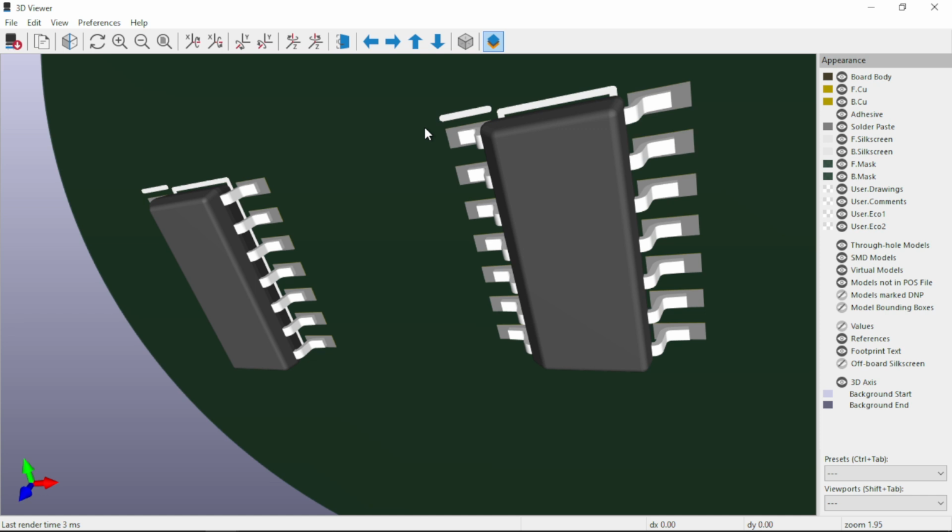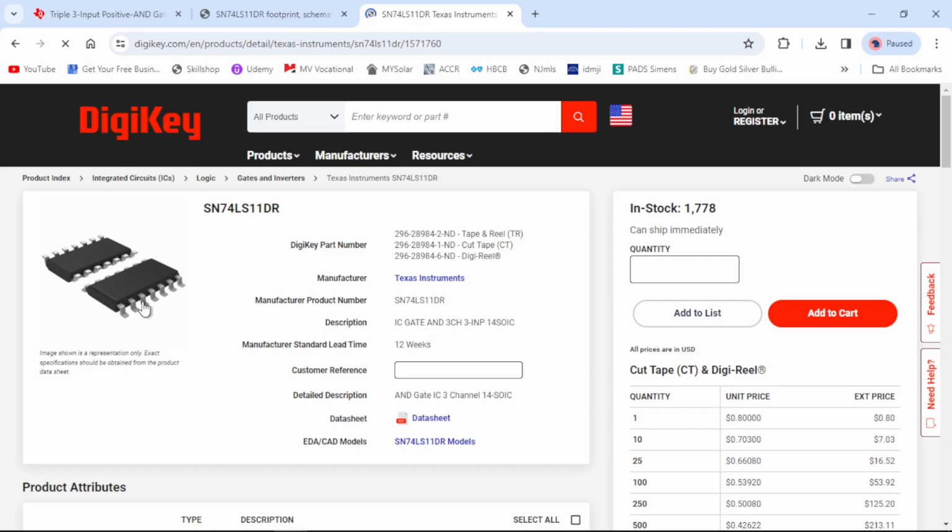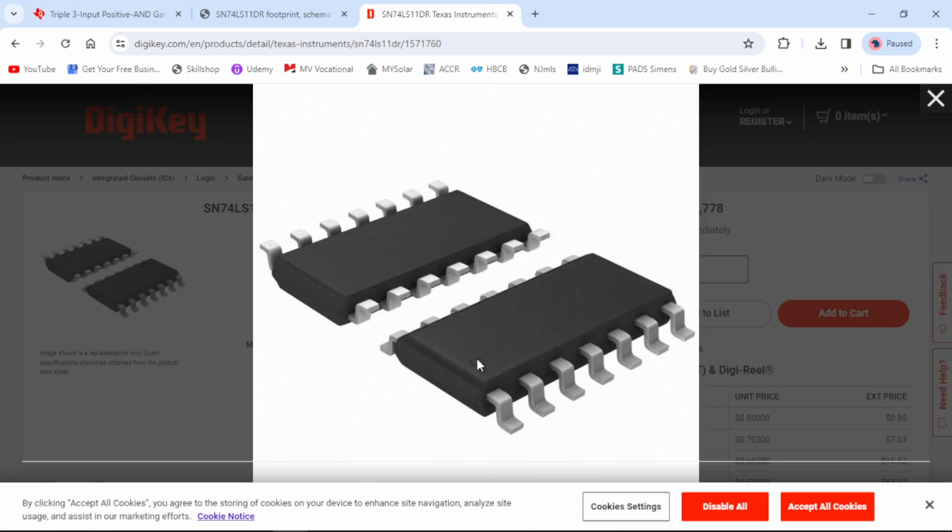Okay. So you see they give you a box. 1, 2, 3. The output's over here, ground over here, VCC over there. Okay, so look at this one. The footprint on this one, they give you one with a dot, and maybe I can use that. So let's compare that. Select format. I'm using KiCad. Step 2. Download it.